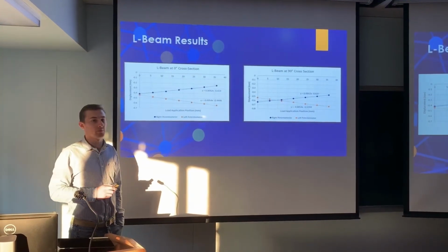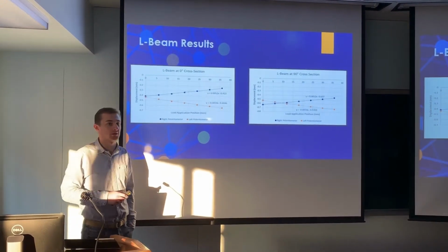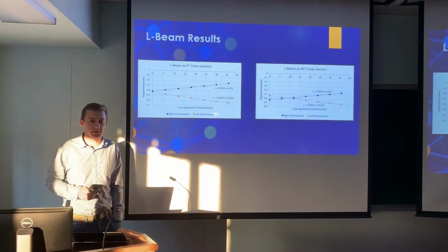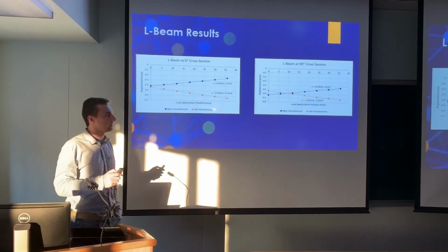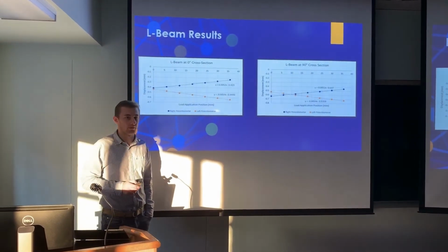These are the L-beam deflection graphs for both orientations. For the L-beam, it was experimentally determined that the shear center was -2.04 and 9.54.